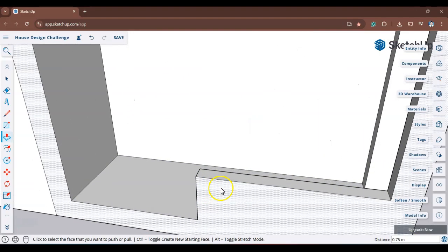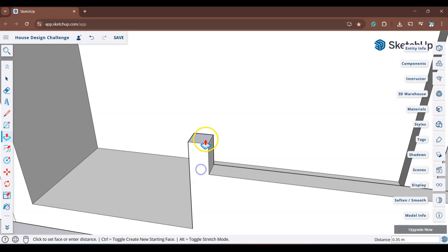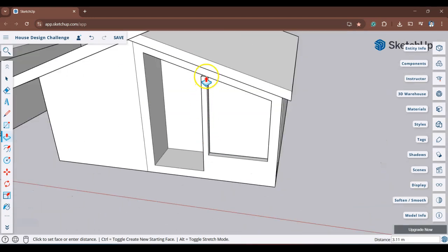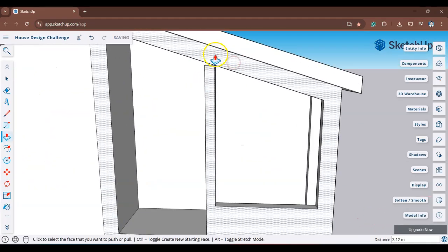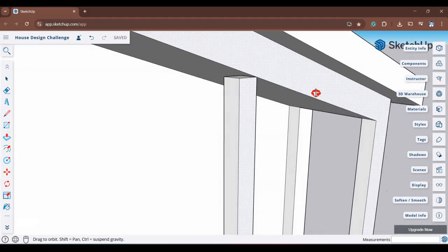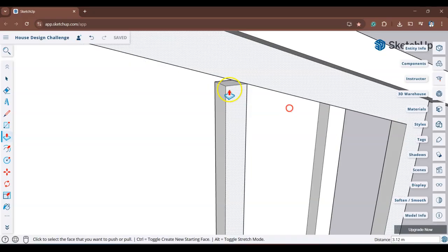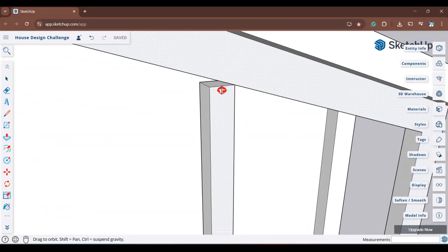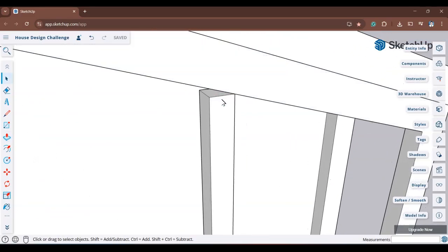And then let's press rectangle again, or R, on the surface right here. I'm going to do on edge square, P for push pull. And we're going to push pull all the way to right here. And notice it gets stuck right there, which is totally fine. I'm going to try something. Let me see if this works.